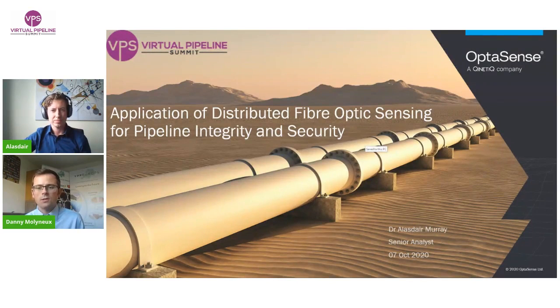Another anonymous question is, can you rely on NPP if it's an old leak, which is getting bigger? Okay, yes. So as I said in the slides, the NPP is the detector that we rely on the most because it occurs instantaneously at the moment of the leak. But if we're talking about a very, very small leak that perhaps doesn't generate an NPP, or if the system happened to miss it, then what happens later on? As I stated, we do have the orifice noise, strain, and temperature change detectors, which augment the NPP detector. And so as the leak grows, these will become more useful.